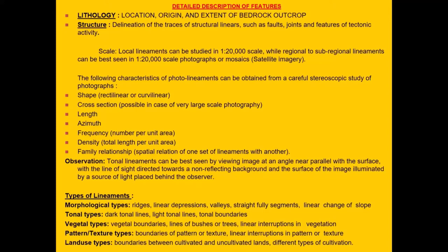Right. So as we know, for lithology you have to get the location, origin and extent of the bedrock outcrop. Then structure wise, we can start with 1:20,000 scale mapping, which is at the reservoir scale. Or if we have to go to the dam site exactly, we may end up at 1:5,000 scale. That detailed scale mapping is also required, because you are constructing a concrete dam upon a basement, and if it doesn't sit on competent rock, there is a heavy chance that it may topple after some time, maybe due to the load of the water, maybe due to the recurrence of seismicity in that area. So anything, you do not know.